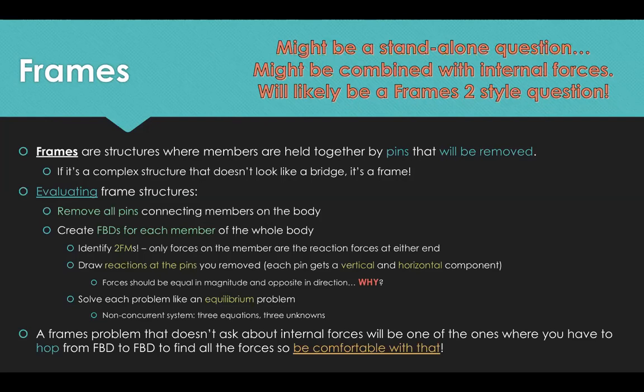But what's nice is that so many of them will end up on multiple free body diagrams, and that makes it a lot easier to simplify the problem. So you can take the moment about one point, find the reaction at another point, and then that gets translated to another free body diagram, which eliminates an unknown on both of them, essentially. So any questions about that?